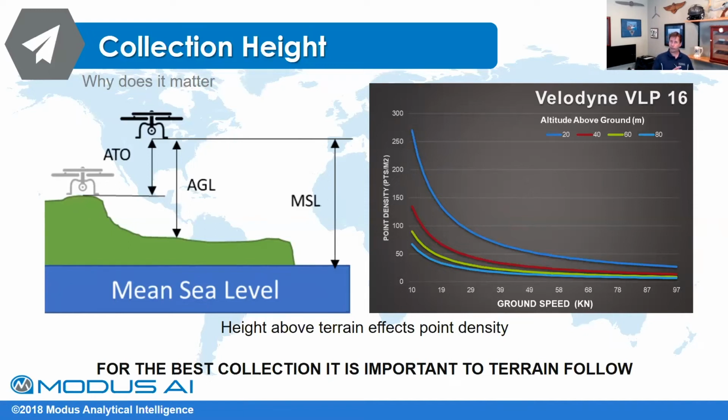So depending on what your point density requirement is, that's one aspect. But the next part is your height and your speed, particularly your height. The reason being, depending on where you're operating inside the United States, like here in the southwest part of the United States, we're bare, we're desert, we can be 20 meters off the ground, it's fantastic. You go up to the northeast or the northwest, now you have tree canopies, you can't see that far, and you have to guess what the tree heights are going to be, 180 feet, 200 feet, and then you have to map on top of that.